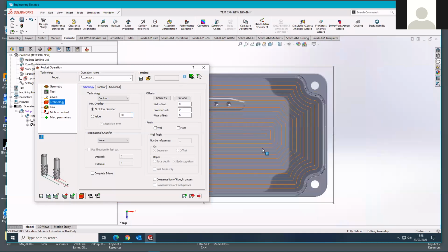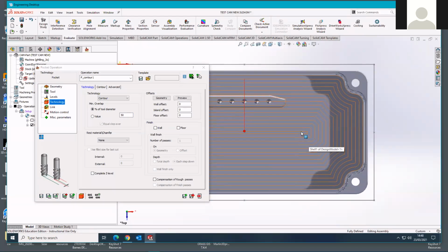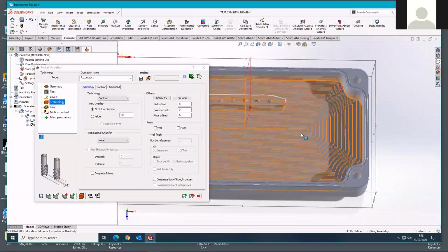So that's all related to the strength of the tool itself. If you're really unlucky, you will push the tool so much that it will snap. But more than that, what will happen before is the tool itself will begin to bend under the force of the material being cut by the tool, and you will achieve inaccurate cuts.